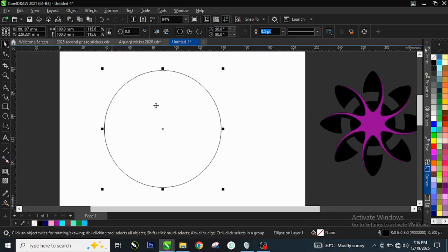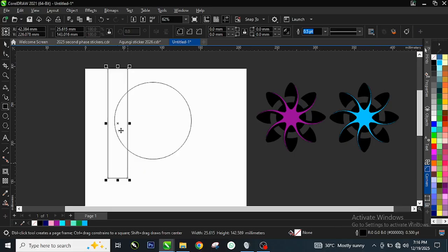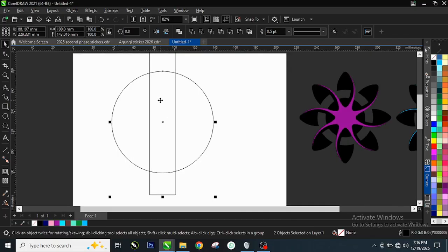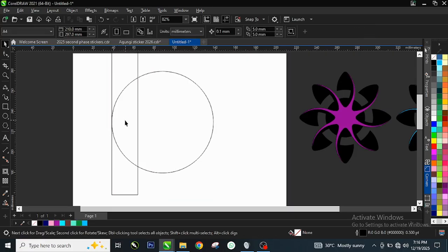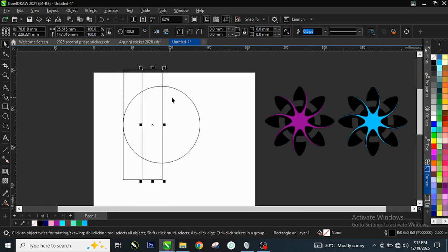The next thing I'm going to do is come down here again and draw a rectangle, something like this. It doesn't matter the size, because we are going to bring it to the center of this and then take it to the left. So Control E and C will bring it to the center, then letter L will take it to the left-hand side. Now click on this edge and hold down the Control key, so that you have a duplicate like this, and right click immediately to have a duplicate. Then Control R will give you another duplicate.